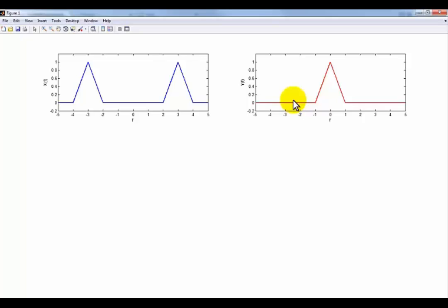And as we discussed before, to do the convolution we basically take the one waveform and flip it in the x-axis, though because this is a triangle it is symmetric. Then we start at negative infinity and slowly walk that signal in, and we look at the area that overlaps between this signal and this blue signal as it marches along with delta F in this example. And what we're going to plot is the magnitude of the area. We're not plotting the multiplication of the two. We basically calculate the overlapping area, and that is what we plot.